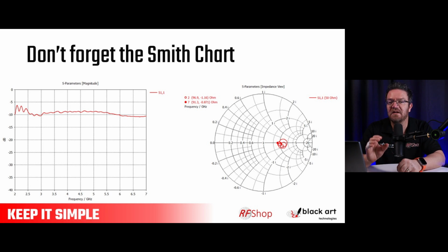And that's that the impedance locus, the actual locus, yes, is around 110 ohm. So it's not on a 50 ohm. It's not hovering around 50 ohm. So if it was hovering around 50 ohm just consistently, you need to think about something else to do. But this one shows the antenna is very consistent and stable. It's just at the wrong impedance.